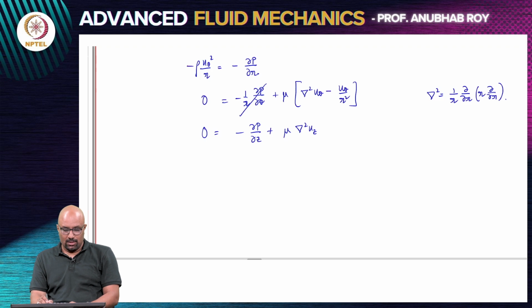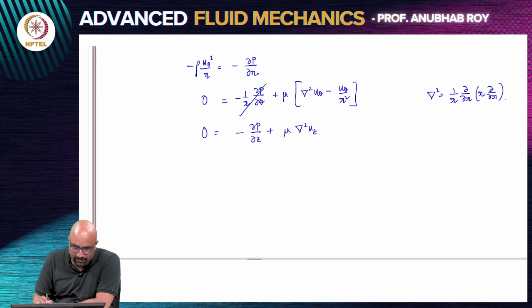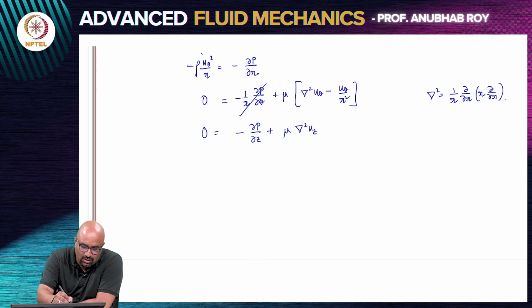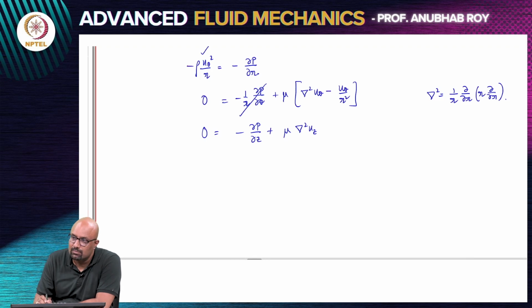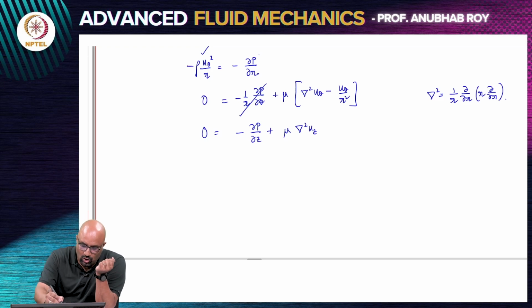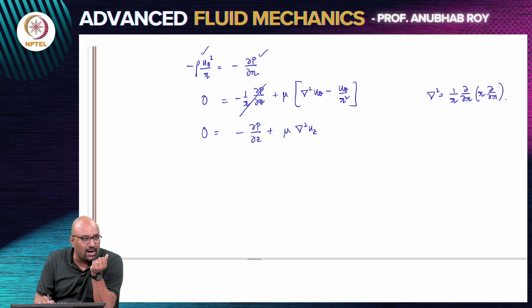Okay. So it's actually a derivative only in the radial direction. So if you were to have an azimuthal flow, some kind of a swirl in the problem, that there was some kind of degree of rotation in the problem, you need a radial pressure gradient to balance this.